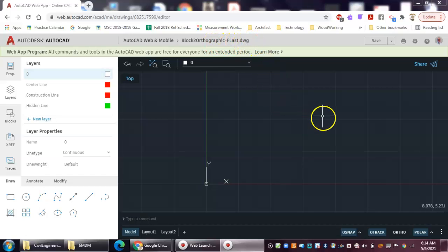At this point, you should be going through these steps in sequence where you come up here and click on the settings. Make sure that your units are at decimal units, 0.3 decimal place. And then, of course, you've developed at this point all of your different layers. Your object line layer is already there.